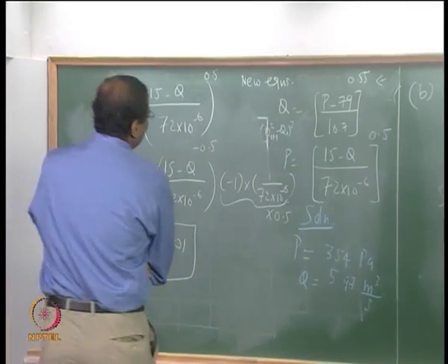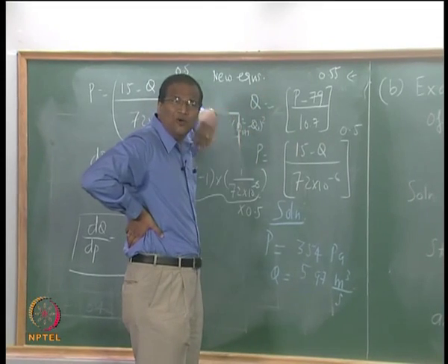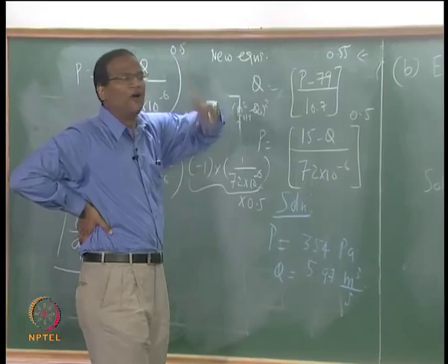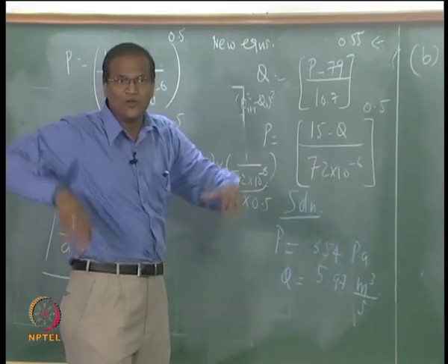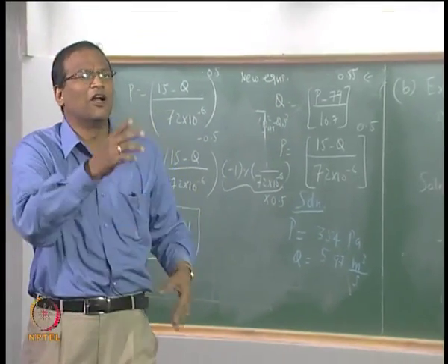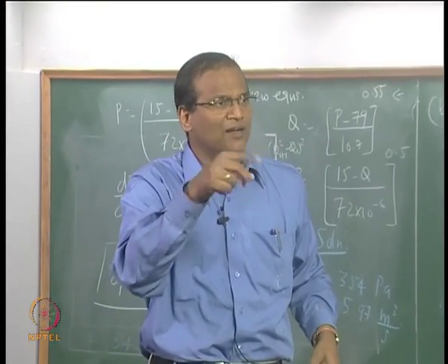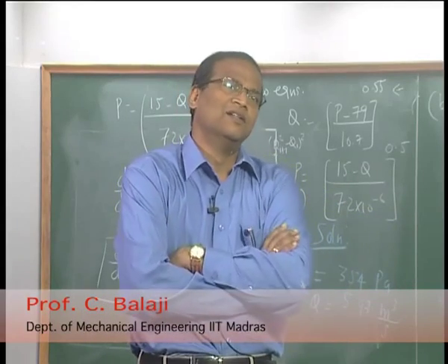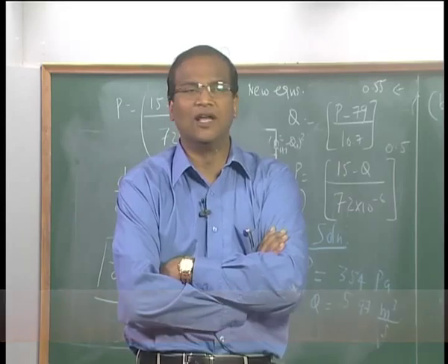So this is a good exercise in the sense that it tells you how to rewrite the governing equations in such a way that even when you are way off from the final answer, because you are raising something to the power of 0.55, it constrains or bounds the errors. Are you getting the point? So you can work out qi and qi plus 1 and delta q, the error, how it propagates, you can write it mathematically, and this is why this information flow diagram works, whereas the other information flow diagram does not.